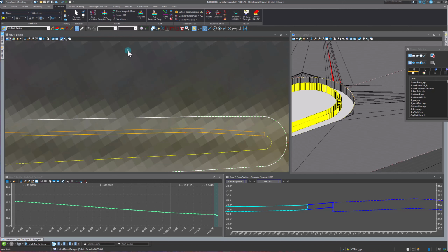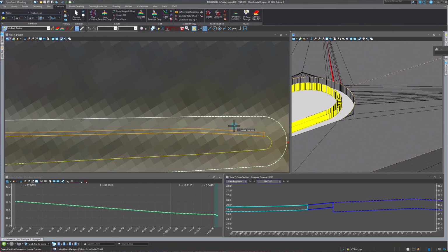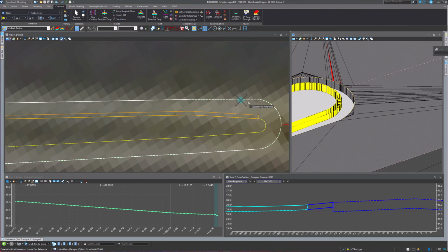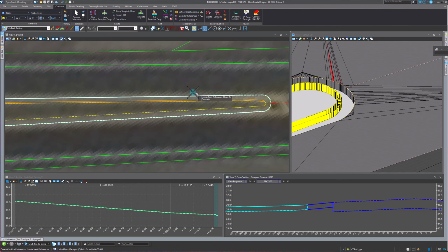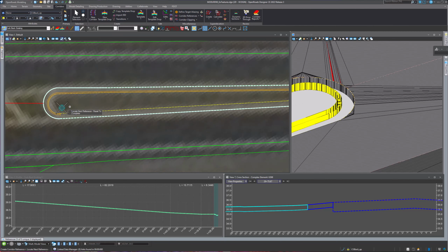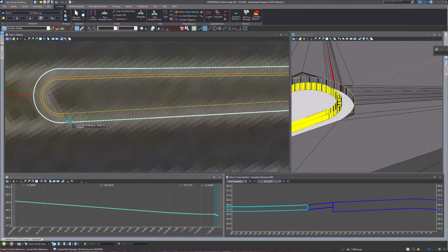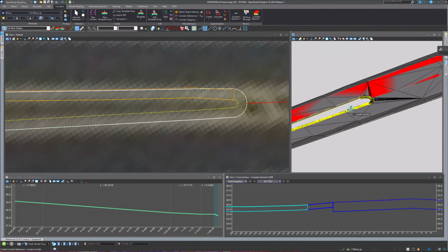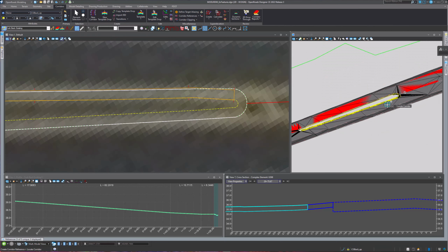So what we need to do is come into our corridor tools, corridor reference, add a corridor reference. So let's locate our corridor. You usually want to click on the red little tabs here, that is the actual corridor. The orange one is the template. And let's select this one. We'll just select all of these so it knows to go. We just wanted to have both of those as a reference, because it may be that it needs both of them to find it. And you can see it goes out and it finds that.